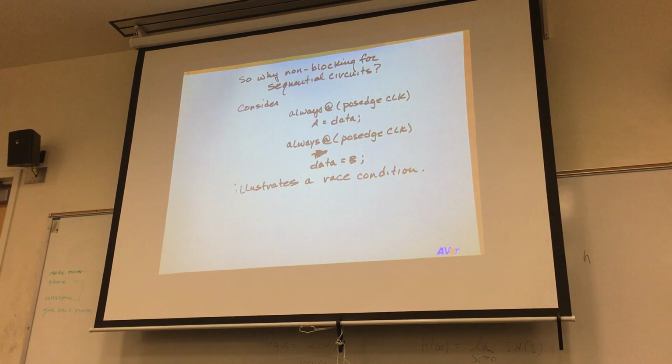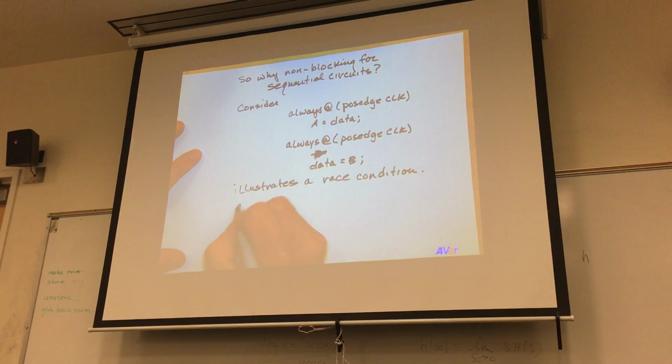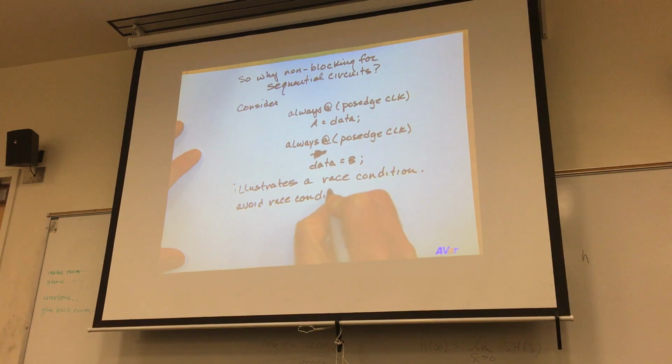So, the way that you would avoid the race condition is to replace both of those blocking assignments with non-blocking assignments.